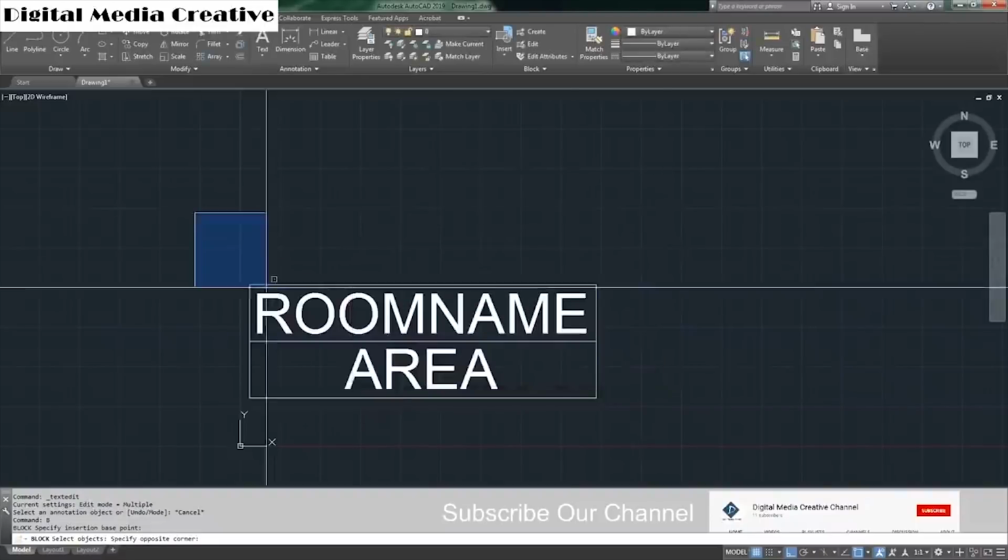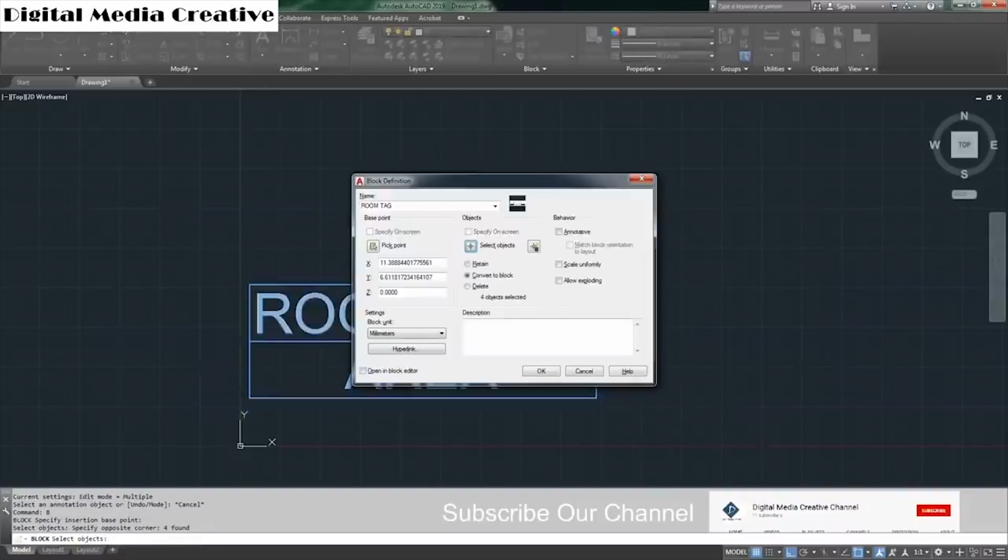Okay, then make sure, you can see the behavior, you don't want to make it annotative. I'll show you annotative in the next stage. The other thing is this Allow Exploding. Make sure it's unticked. You know why? Because if it's ticked, anyone can explode your standard block once you've made it.